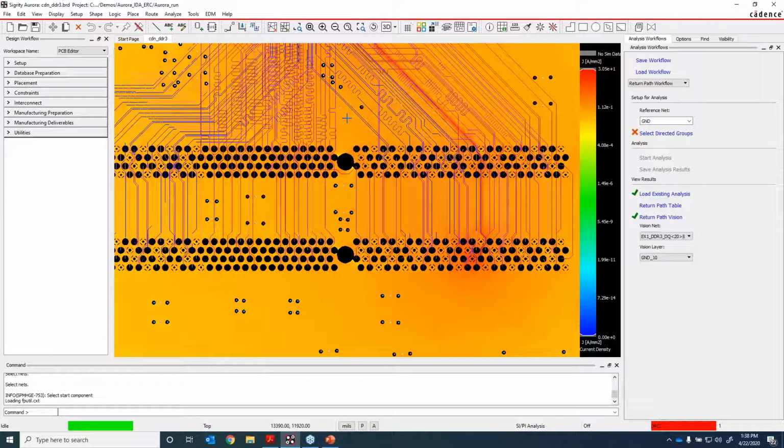Most all of that is set up in the constraint manager, where, when you lay down your trace runs, each particular layer can have a variety of constraints set up so that you know you're within a certain width and things like that. All of that is set up in the PCB editor tool, just as you would normally. There's no other special work you need to do to define parameters for the impedance flow. It just goes by the constraint manager settings for trace width, the amount of copper on the layers, the layer depth, the layer widths, things like that.